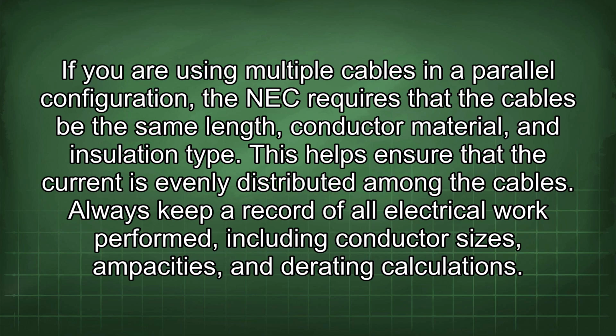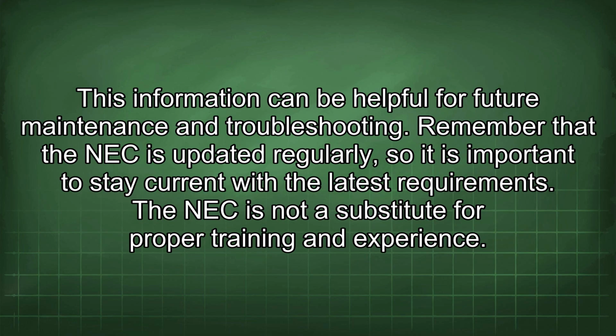Always keep a record of all electrical work performed, including conductor sizes, ampacities, and derating calculations. This information can be helpful for future maintenance and troubleshooting. Remember that the NEC is updated regularly, so it is important to stay current with the latest requirements.